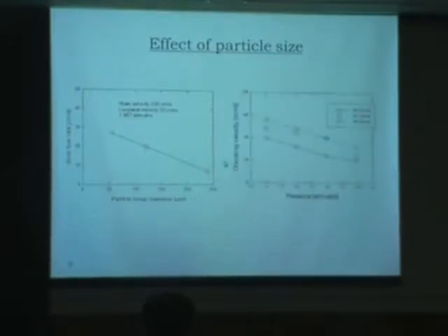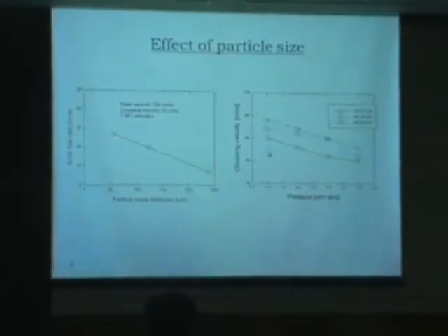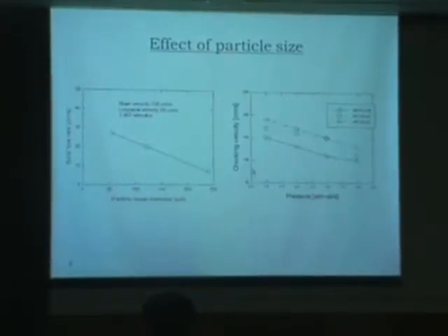In this study, we also calculated the choking velocity, the velocity at which this circulating fluidized bed is no longer considered a circulating fluidized bed system. The circulation of the particles is hardly there, and the effect of pressure was observed.